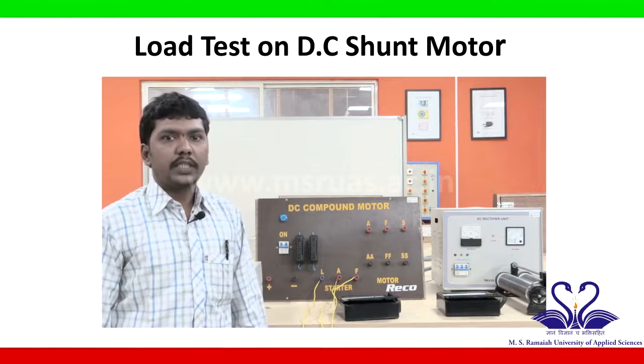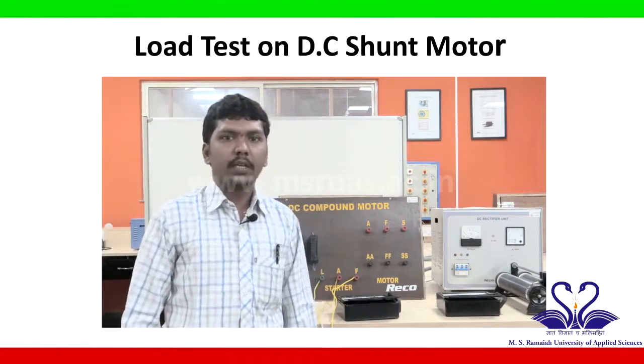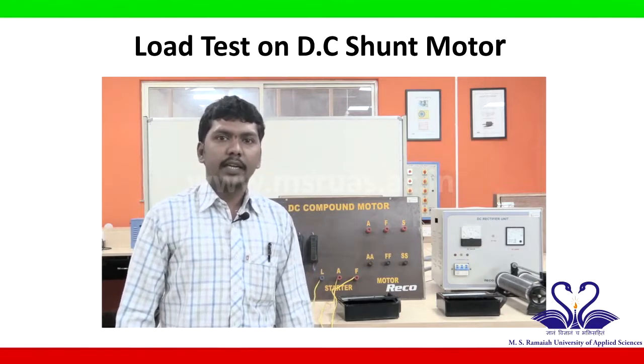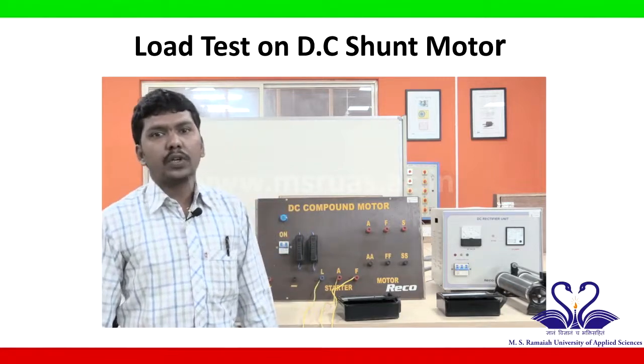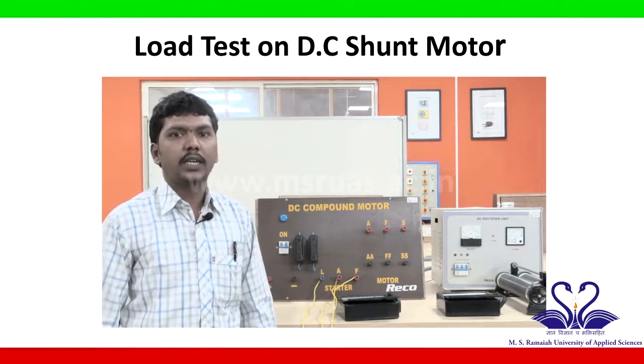In the case of DC shunt motor, the field winding is connected in parallel with the armature, whereas in the case of the DC series motor, the field winding is connected in series with the armature. And in the case of the DC compound motor, as the name itself indicates, it is the combination of both series and shunt.